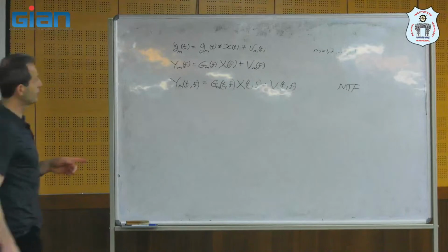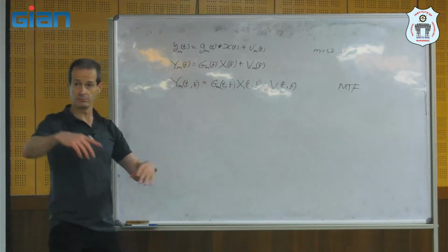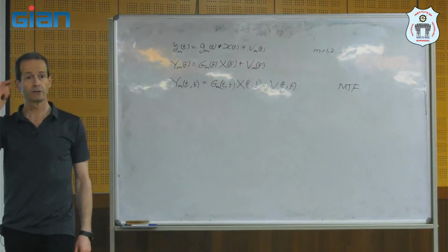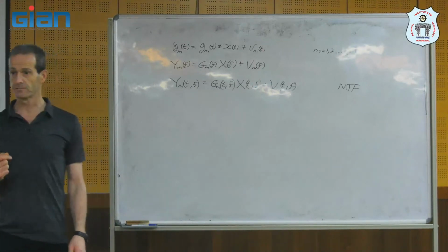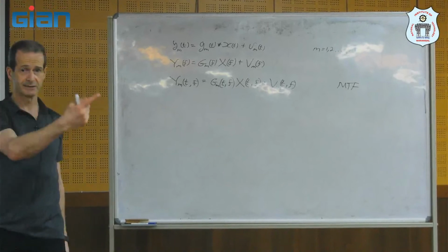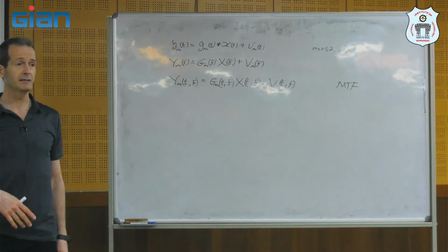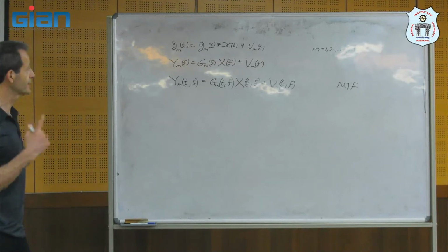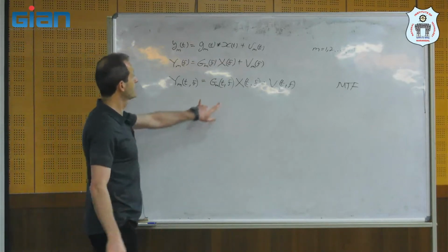But the impulse response in the room, for example here, when I speak, if you put a microphone on when you listen to my speech, the impulse response in this room can be hundreds of milliseconds. So it's much longer than the length of the window.